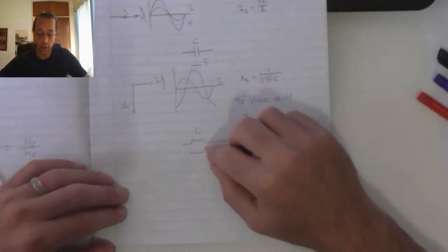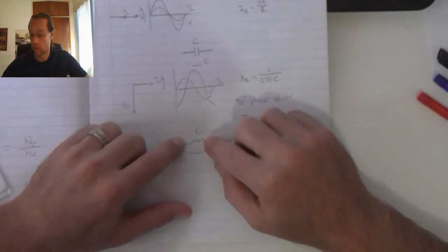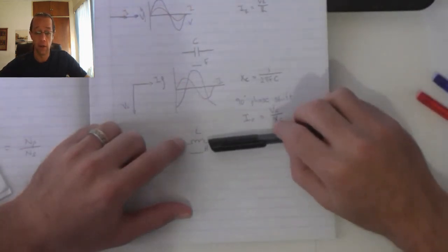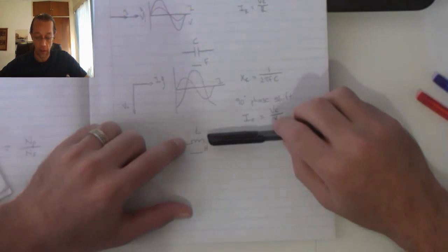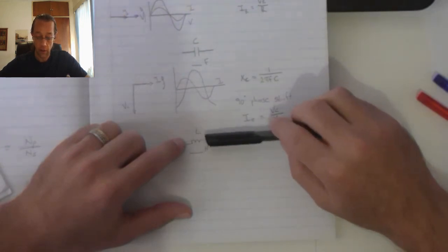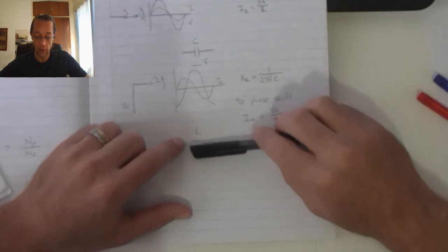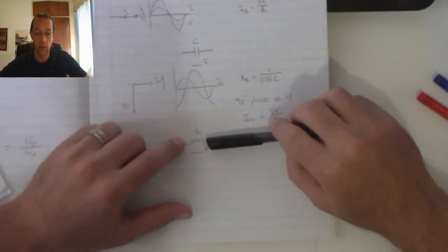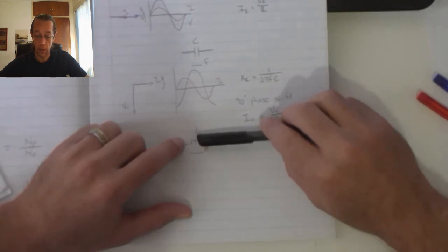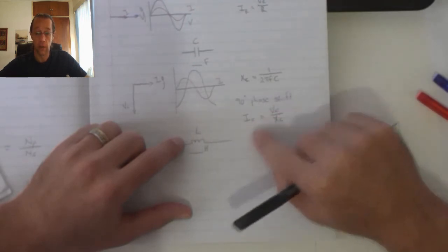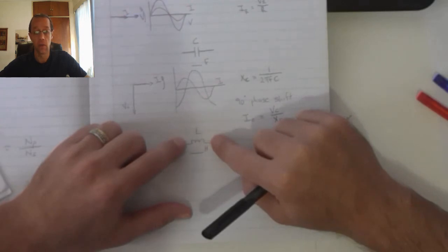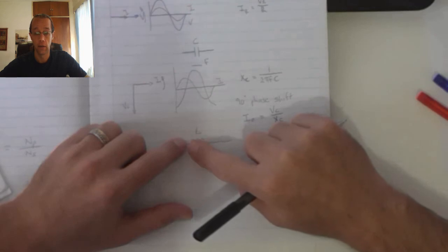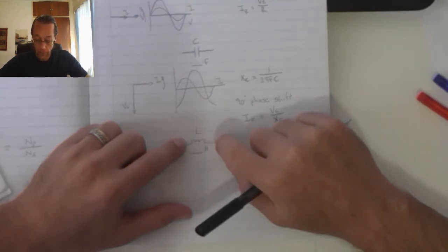Again, it's a reactive component because the inductor is nothing more than a conductive wire that's wrapped around a core. Now, in theory, that means I should have 0 ohms, or almost 0 ohms on my coil. But if I apply Ohm's law to my coil using the almost 0 ohms there, what is going to happen is I'm going to get almost infinite current.